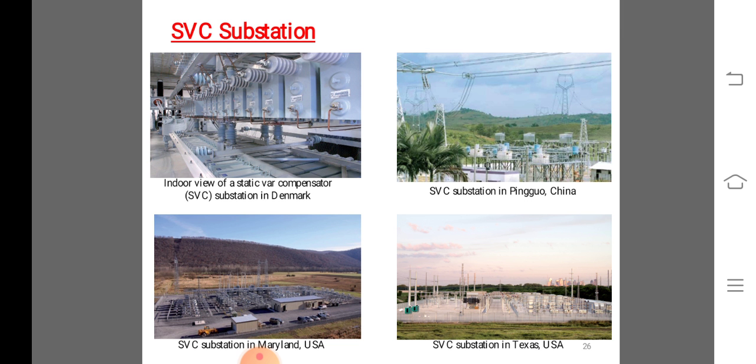Electrical arc furnaces impose extremely difficult service requirements on electrical power systems, since the changes in arc furnace load impedance are rapid, random and non-symmetrical. A three-phase static VAR compensator can be located independently so that it compensates for the unbalanced reactive load of the furnace, and the thyristor controller will respond quickly in order to minimize the voltage fluctuation or voltage flicker seen by the system.